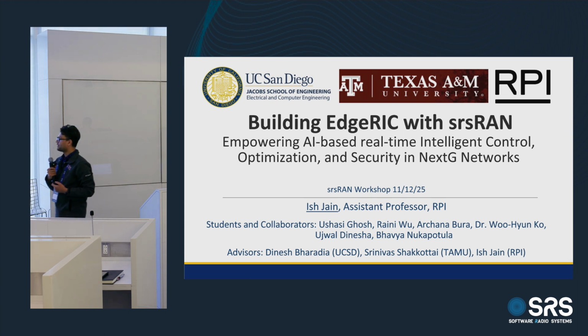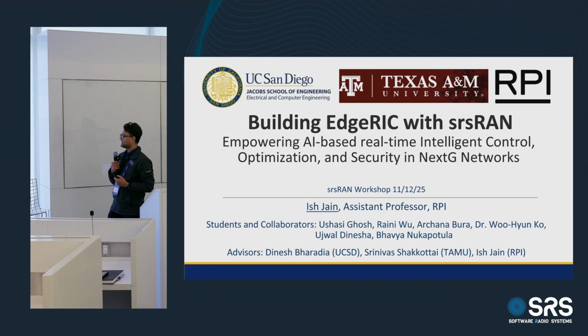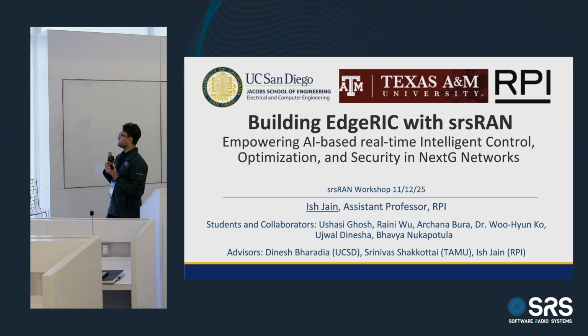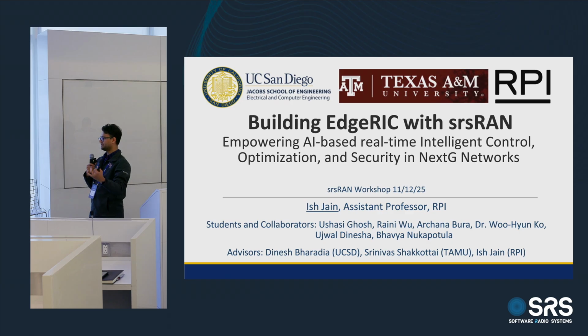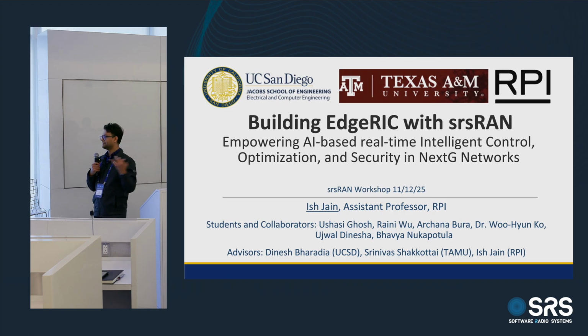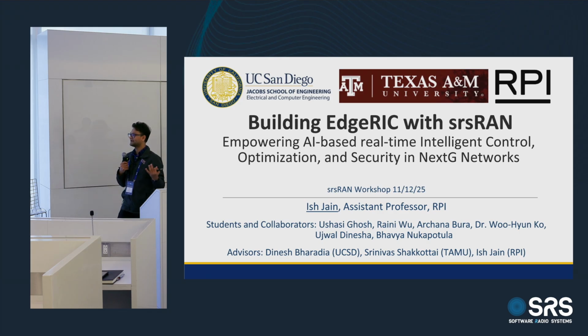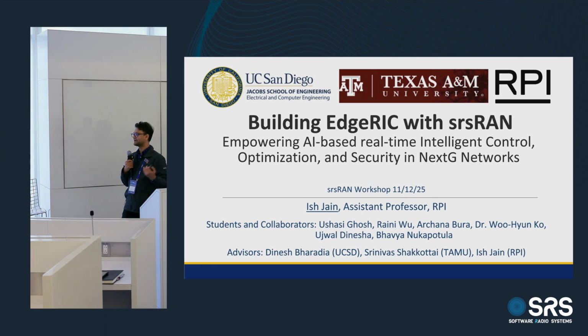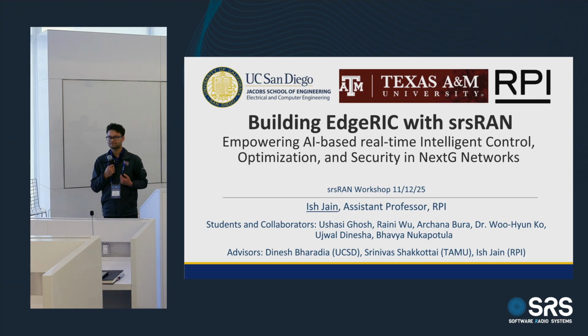Does Beam Armor work with the 7.2 split? Right now we are working with full srsRAN, but the answer is yes, it will work with this split, because we are looking into the beamforming or scheduling decisions which are part of the DU. So it will work with any RU out there, as long as it provides the channel estimates to the DU for implementing the beamforming policy and the entire scheduling framework which is available in the DU. We are envisioning this as a framework which can integrate tightly with your DU, and it has access to channel and scheduling policies.